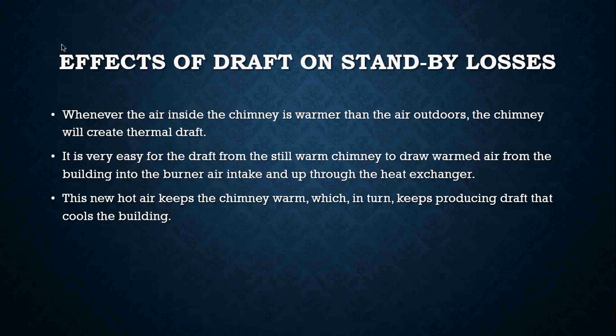We still are, simply due to the fact that we have a warm chimney. That temperature difference is going to create a thermal draft, which is why standard open fireplaces without a fireplace cover are very, very inefficient. They actually suck more heat out of the building than they heat the home.